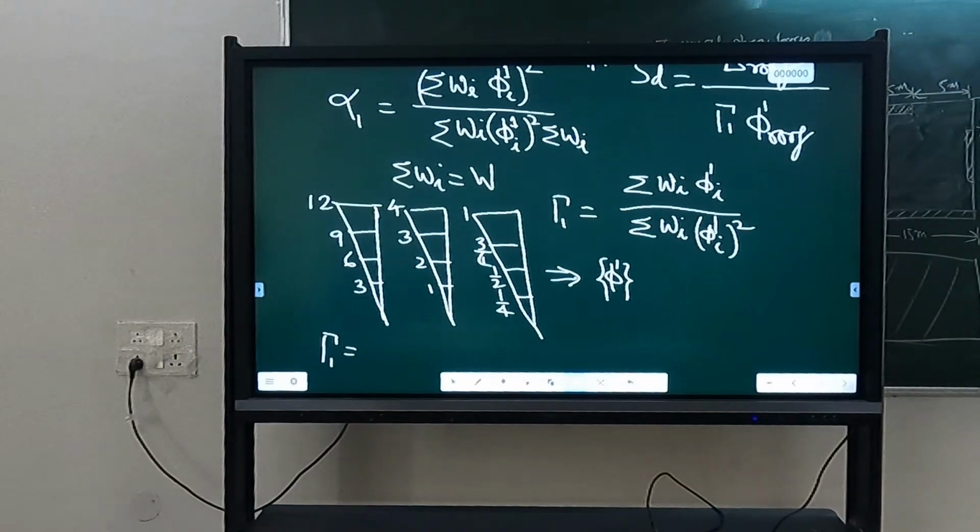There may also be some additional hidden strength, because you might have provided reinforcement more than what was calculated for VB. And then you have used strong column weak beam design, so the size of the columns might have been increased more than required due to capacity design.